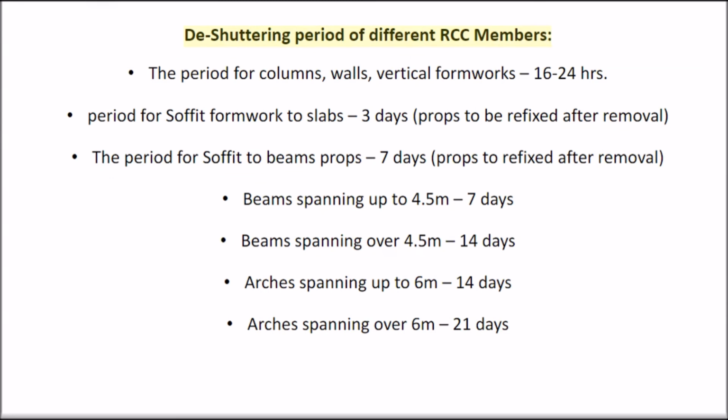De-shuttering period of different RCC members. The period for columns, walls, vertical formworks, 16-24 hours. Period for soffit formwork to slabs, 3 days, props to be refixed after removal.